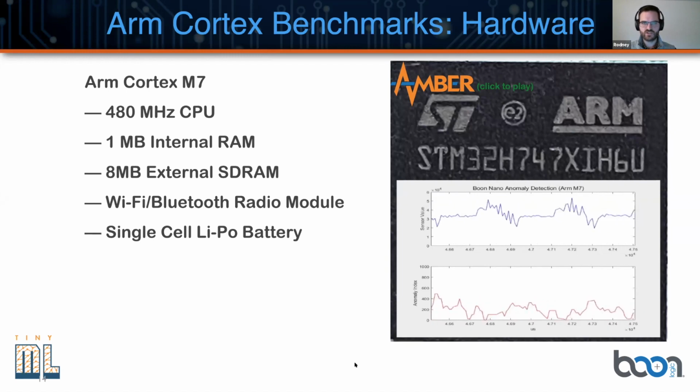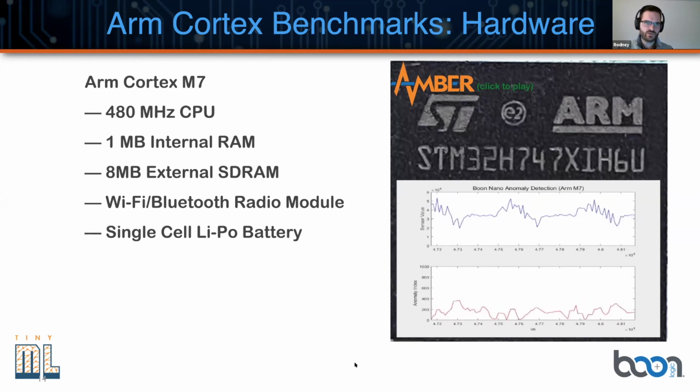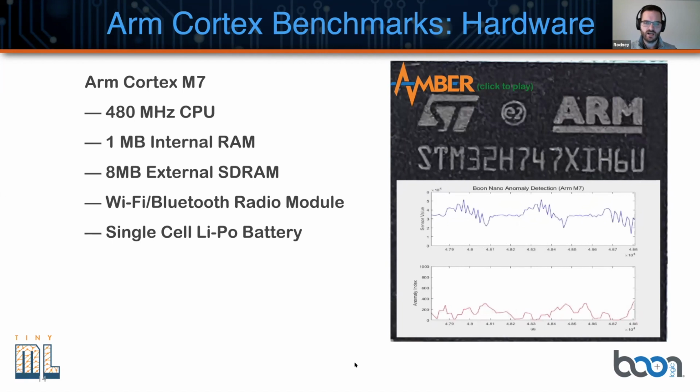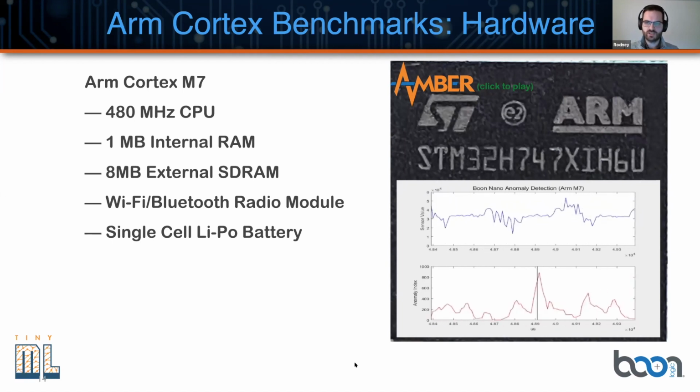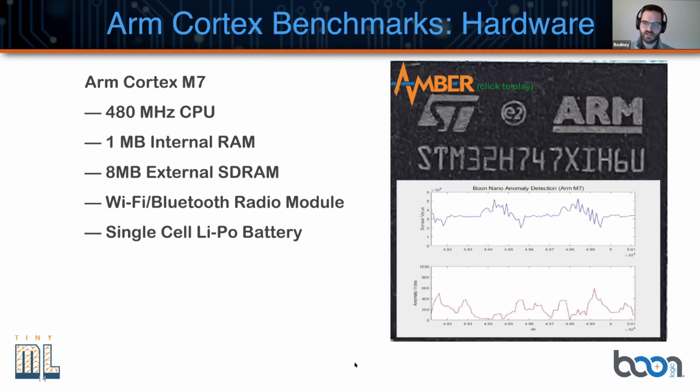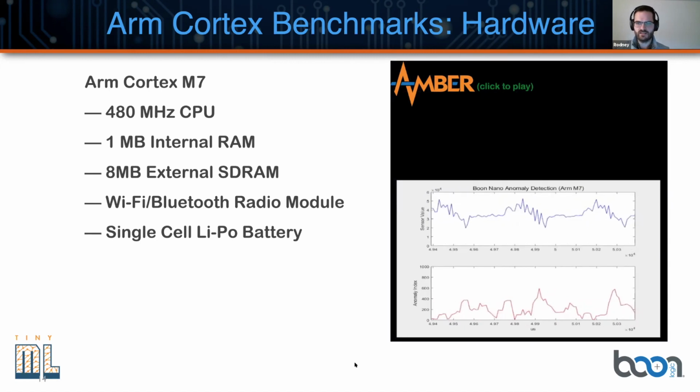So on board this chip, we have those same early auto-tuning and learning phases. But what you're seeing here is once those are completed, we're just looking at that raw data and looking at the anomaly index. So in normal operation, what we would do is, again, threshold that anomaly index. And if it spikes, we'll alert an operator via that wireless radio. So Brian, if you want to go to the next slide.